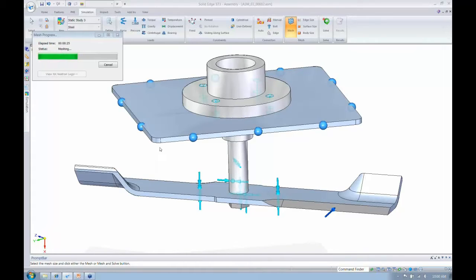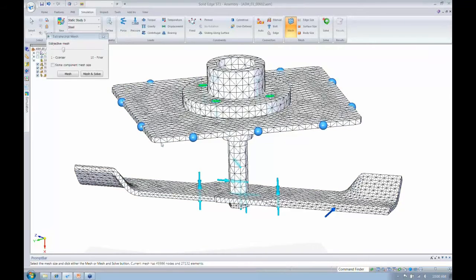Now when this comes back, you're going to see that I'm just going to have one. That's why our rule of thumb is always have 2 or 3 elements through the thickness here. But because I happen to know with this situation that this plate doesn't contribute very much to bending, the plate doesn't bend very much, which doesn't contribute anything to my stress and my displacement here. I've run it with 3 elements, 2 elements through the thickness, and there's no significant change in my results. So I can just use this one element, which is why I did not use those surface elements.